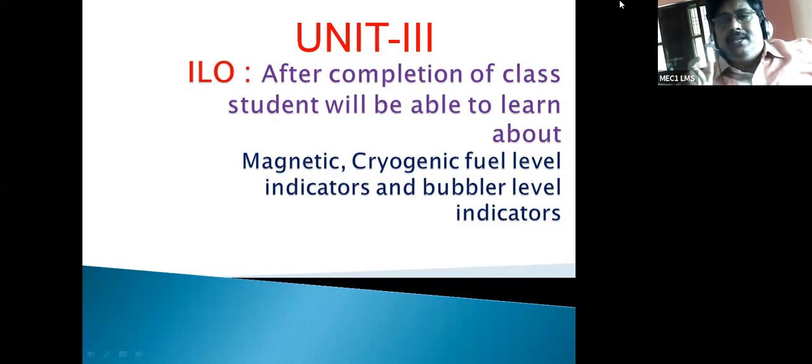Here A is the cross sectional area or overlapping area, and d is the distance between the two plates of the capacitor, which we are dipping into the liquid containing vessel whose level has to be measured. The distance is maintained constant and the area is also constant. There is no movement. But the liquid level changes.